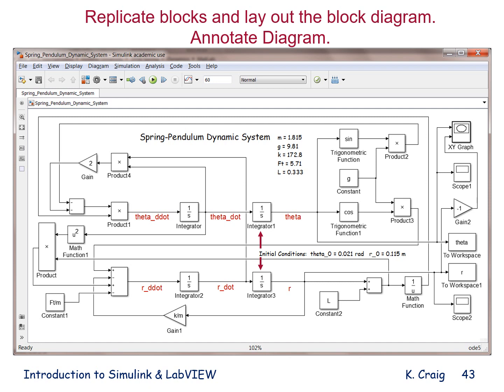Note here that for each integrator, there has to be an initial condition on theta dot, R dot, theta, and R. For theta dot and R dot, the initial condition is 0. The system starts with 0 velocity in the R direction, 0 velocity in the theta direction. The initial conditions are on theta and R, and depending on which of the videos you want to do a simulation of, they each have two different sets of initial conditions.